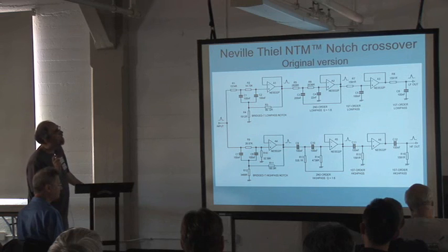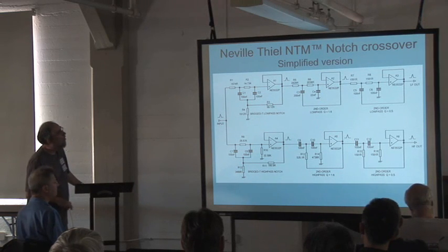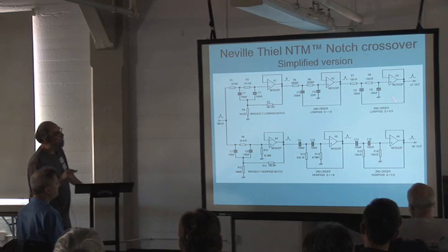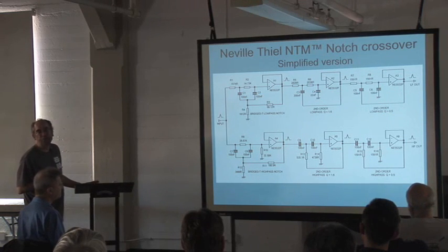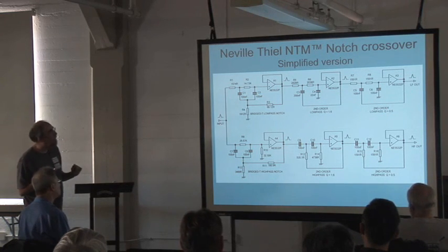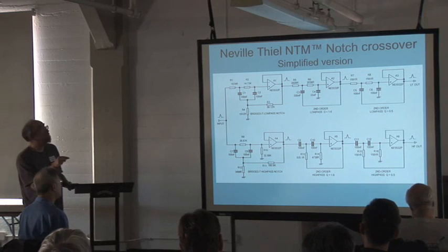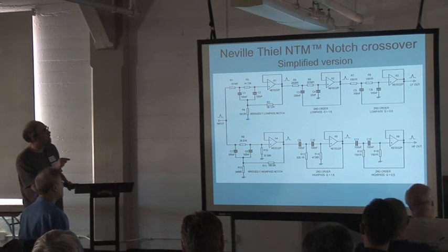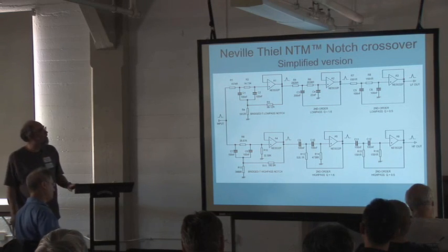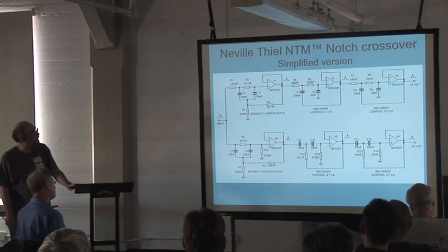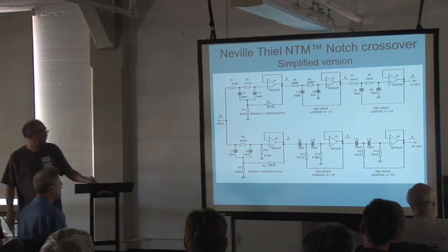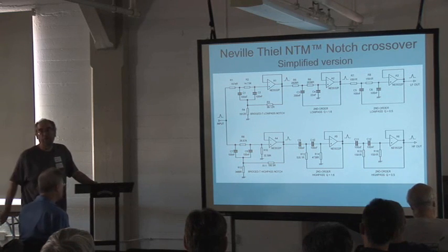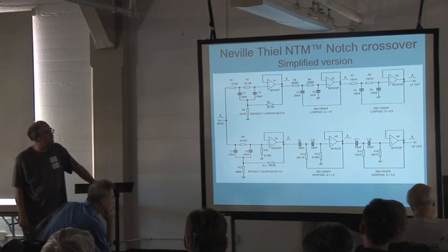So next, please. So, simplified version. You've got a second-order low-pass filter now, instead of 2 first-order filters. If you make that with a Q of 0.5, then that is exactly equivalent to 2 first-order filters, one after the other, and properly buffered from each other. And you've saved an op-amp, basically. So that is my homage to Neville, as it were. That is my version of his crossover. I have not actually put it into a loudspeaker, I must tell you. I'm not a loudspeaker designer. But I offer that to the world, if they want to try that as my interpretation of what Neville was doing.